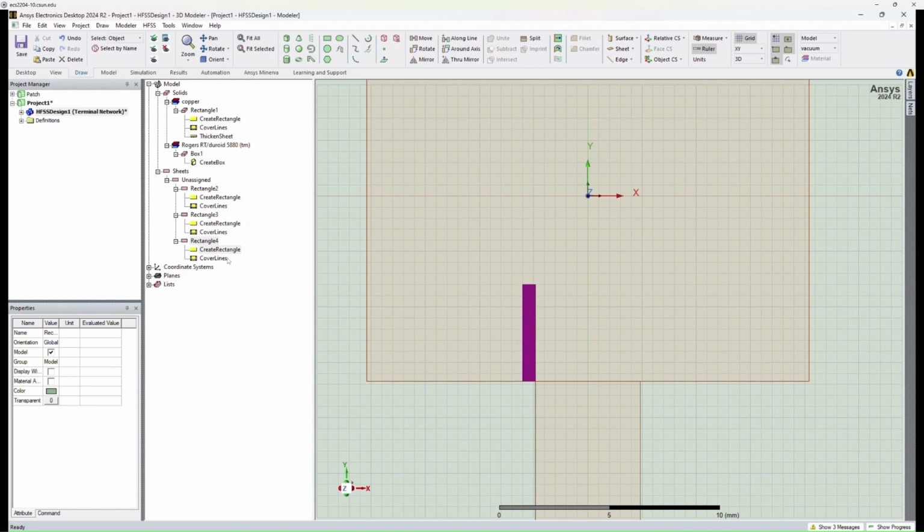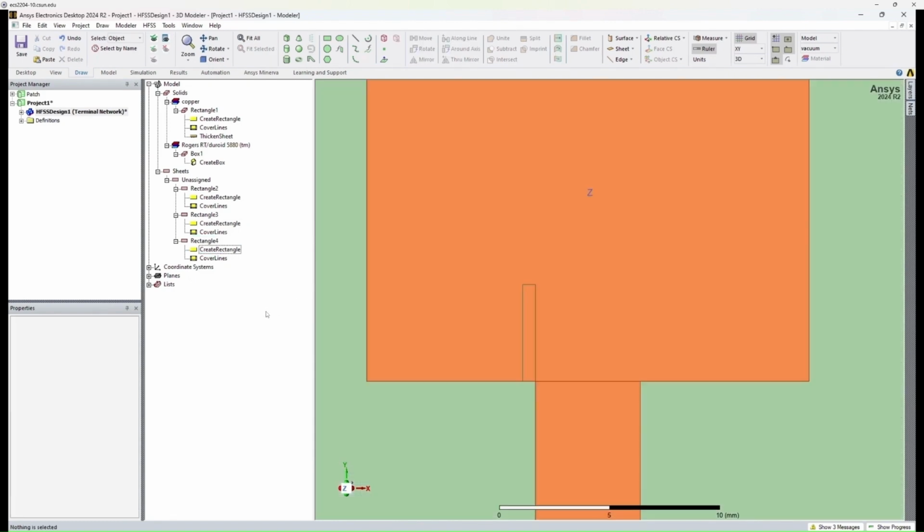going to be. I'm going to go ahead and lay that down, and then we're going to dimension this rectangle to be the dimensions of the cut itself, and then rather than leave it there, we're going to use it as a subtraction from the patch using this subtract command that we currently don't have highlighted. That'll allow us to take away the shape of this little rectangle from the patch, and that's how we're going to define the inset gap of the antenna.